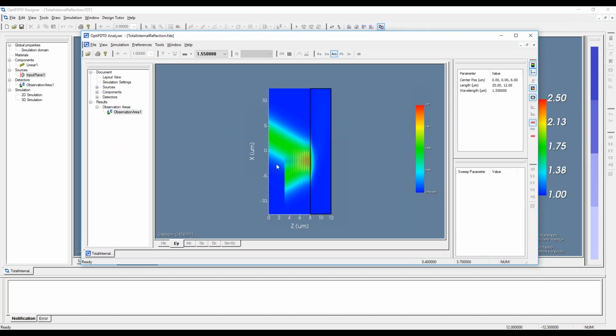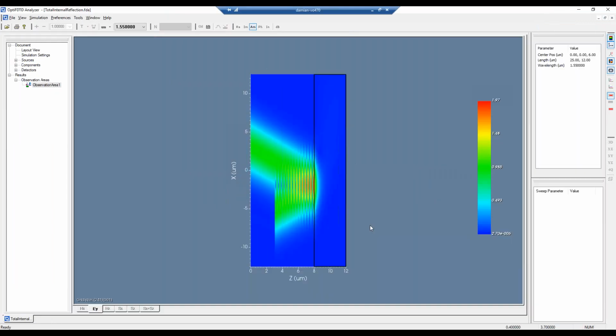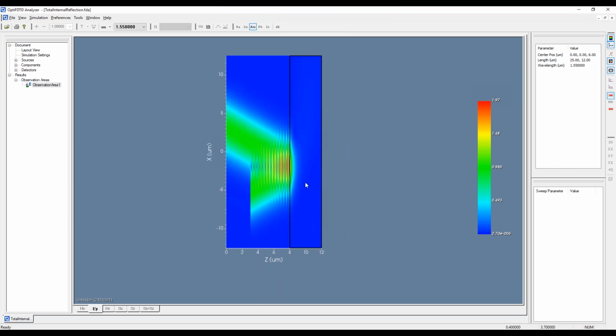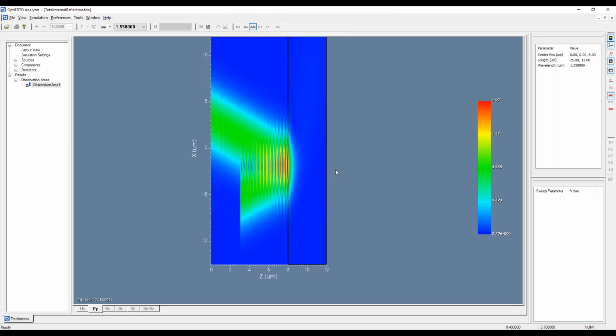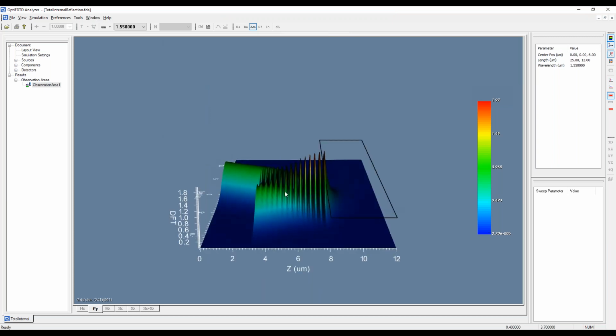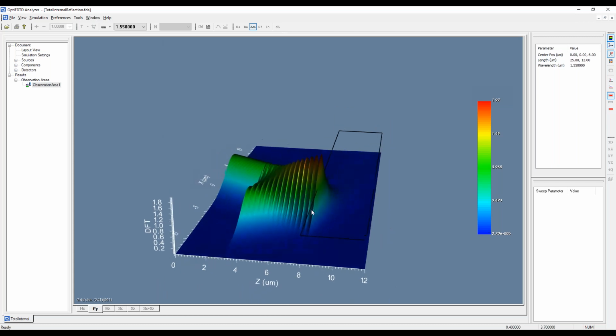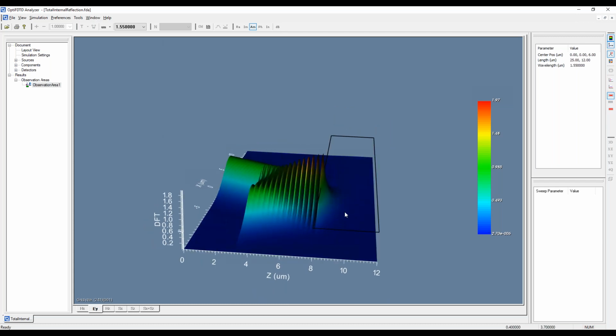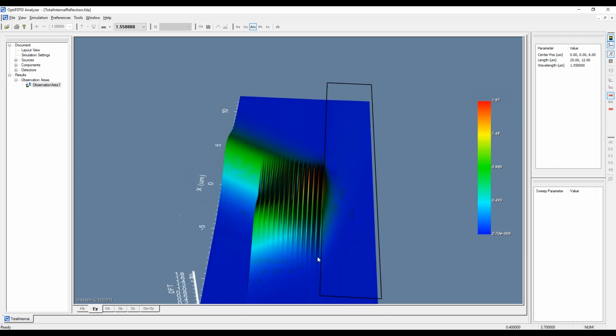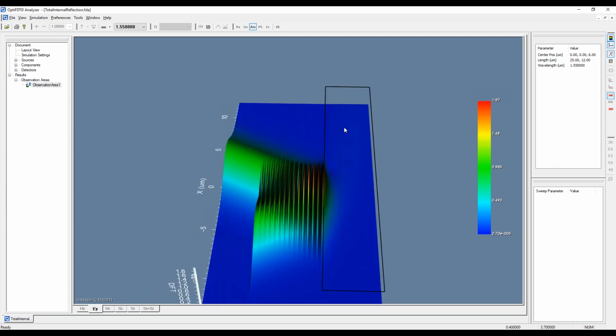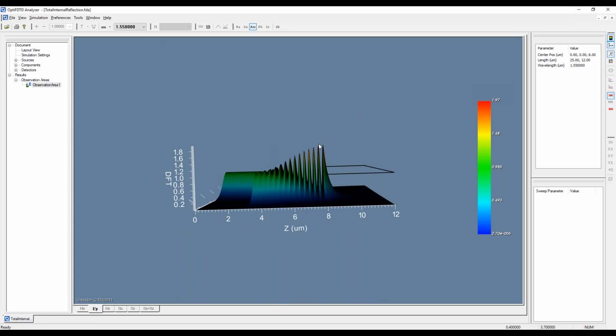So here I increased that angle there and went past the critical angle. And now we see it's almost completely reflecting off this boundary, right? We get a little bit of this penetration into the secondary material here, but by far most of it is reflecting. And you can think about this as sort of an evanescent decaying wave, right? It's almost like a waveguide mode, right? The core doesn't confine the light entirely. Some of the wave is decaying in the cladding.